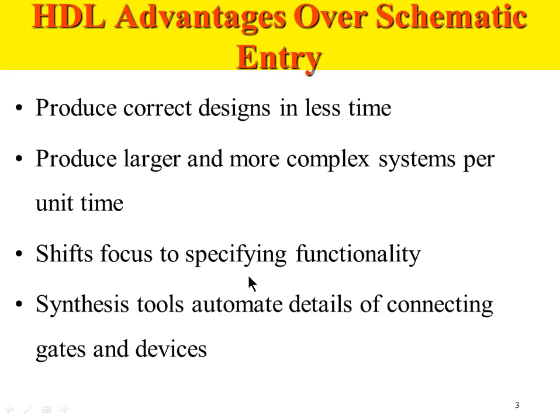So our energy and time as a designer is spent on the functionality, which is the right thing to do. The synthesis tool will automate the details of connecting gates and devices. The synthesis software will take the Verilog design as the input and convert it to gates and the overall netlist, which will consist of gates and interconnections between gates and other components.